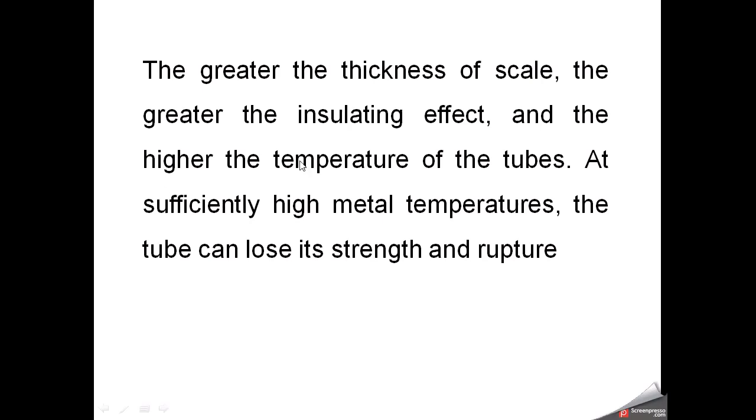The greater the thickness of the scale, the greater the insulating effect, that is, less heat transfer takes place, and the higher the temperature of the tube. When less heat transfer takes place, the temperature of the tube increases. At sufficiently high metal temperature, the tube can lose its strength and rupture. This is a big problem.